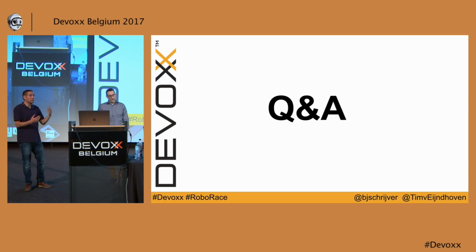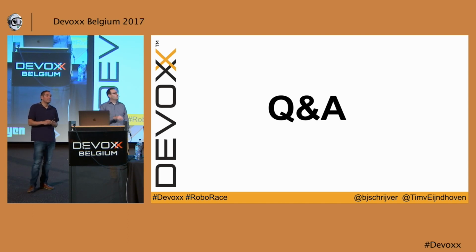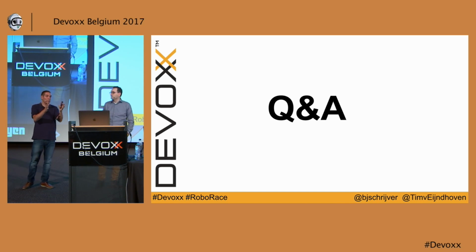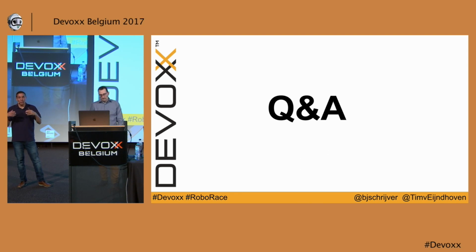Yeah, by recording stuff. We record the races that it does, and we can do the whole computer vision analysis, not only on the live webcam feed, but also on those videos. So that way we can get feedback on our thresholds. And in terms of development speed, when we develop, we try to run as little as possible on the Pi, because that takes a while to copy there and to deploy, and run as much as we can on the laptop. We can just restart the Java process there. So it's this combination of running the least amount of software we can on the Pi, the rest on the laptop, and finding ways where we can build and test stuff without running the car, by recording videos and stuff.